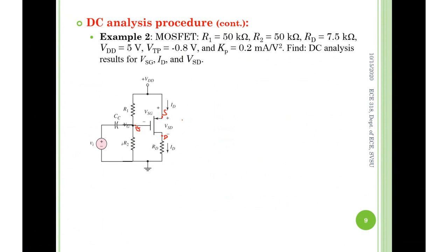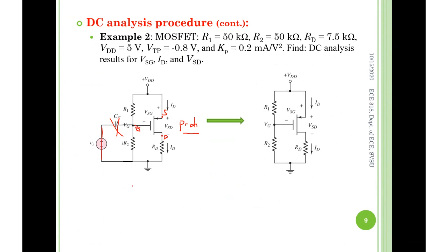And therefore, is this an N channel or P channel? Of course, this matters. It's absolutely a P channel, because this result determines what formula we should use. So for the DC circuit, the first step is: open here, short here. Here we go.